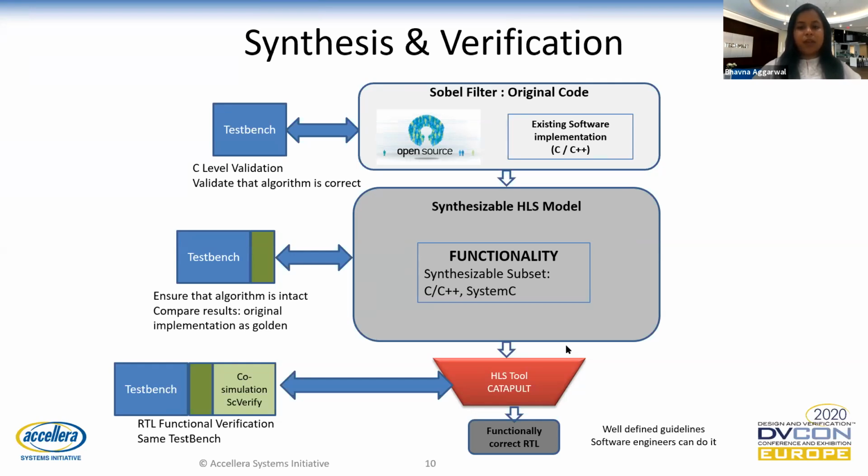Here are the answers. High-level synthesis provides a co-simulation verification environment, also called SCVerify, that uses the same C++ test bench to verify both the hardware and the software behavior. Thus, one C test bench and one SystemC test bench are required to functionally validate the C design and the SystemC IP respectively, and the same test bench was utilized to functionally validate the generated RTL. Thus, no new UVM or SystemVerilog stimulus was required.